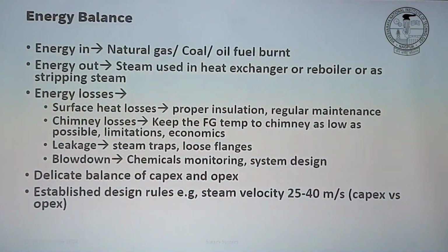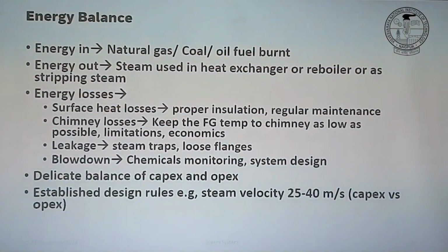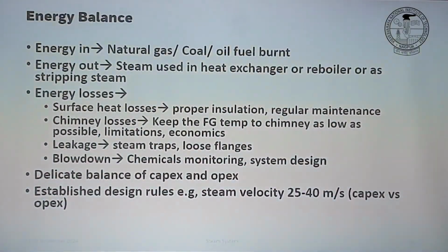Sorry, there is a critical thickness of insulation. So it's not always the case that increasing the insulation thickness makes your heat loss go down. Sometimes it even increases, because you are hindering the heat loss but also increasing the area, so the heat loss, which is Q by A, means that if the area increases, your Q also increases.